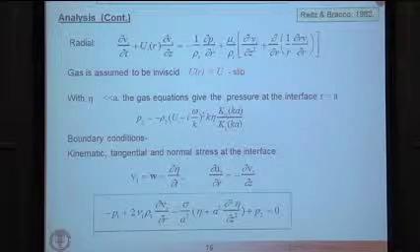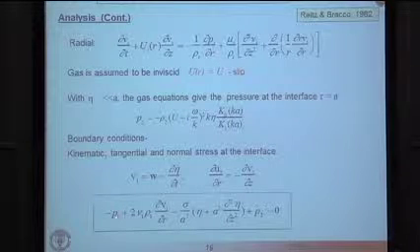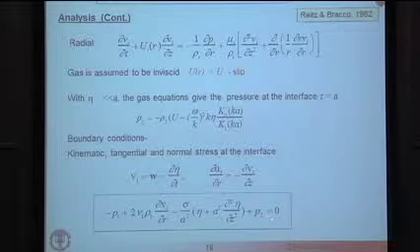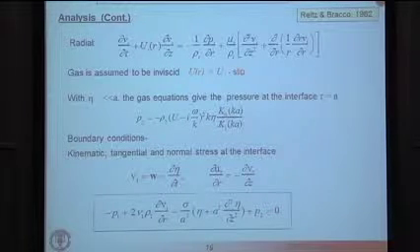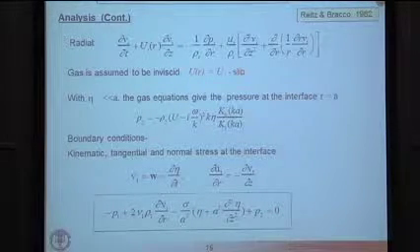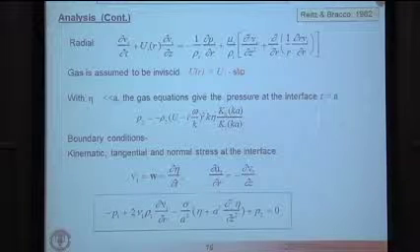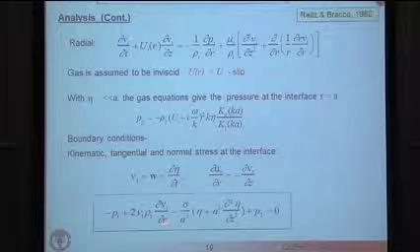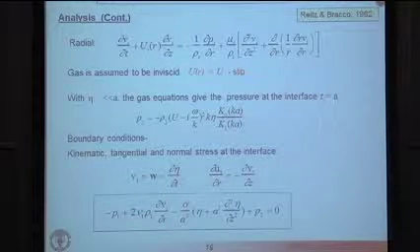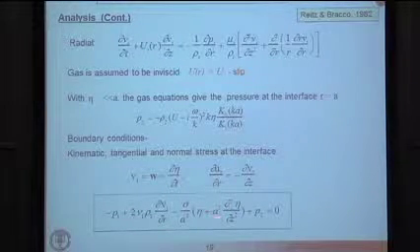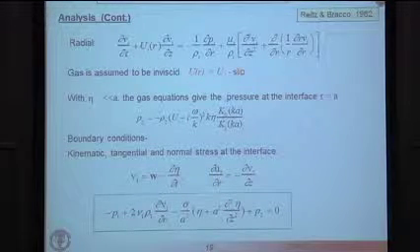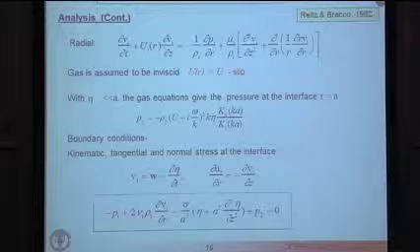And then finally, the most important equation in the box here. This is the normal stress balance. So you can see the pressure in the liquid phase and the pressure in the gas phase. Of course, if you didn't have any viscosity effects or surface tension effects, they would have to be equal. But because we've included the effects of the liquid viscosity, there's a normal stress due to liquid viscosity. And then surface tension is applying another force at the interface that appears in this normal stress balance.